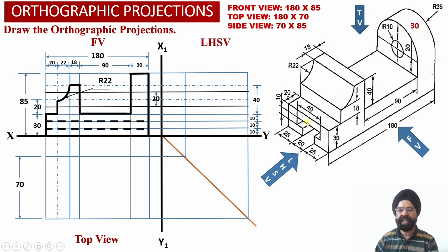Another thing, we know that this horizontal surface corresponding to the T-slot, this horizontal surface corresponding to the top of the T-slot, these two horizontal surfaces will not be visible to the observer from the front view orientation. So we are going to obtain hidden line projections corresponding to this surface and this surface of the solid, which is available with us corresponding to the presence of the T-slot onto the base of this engineering object.